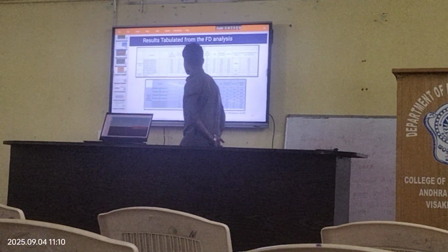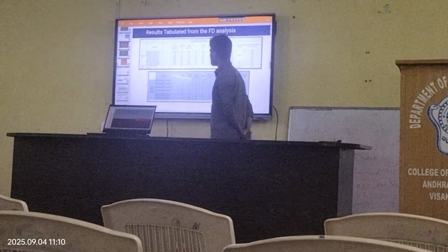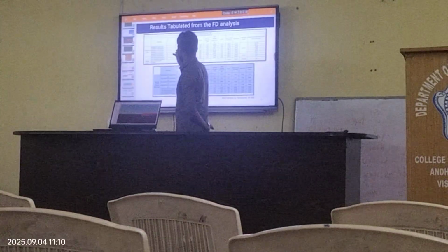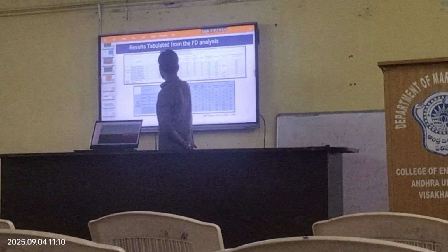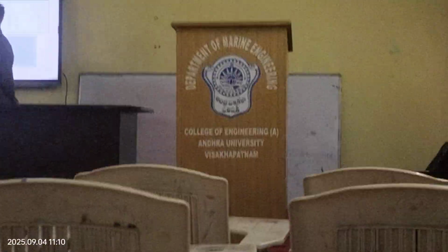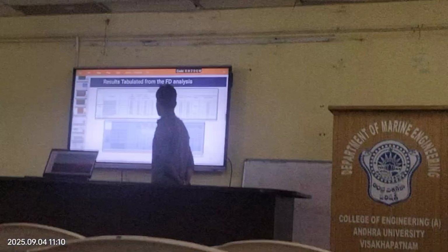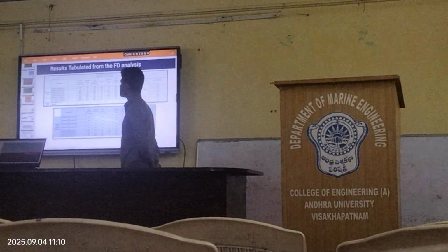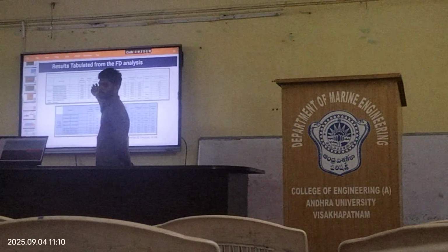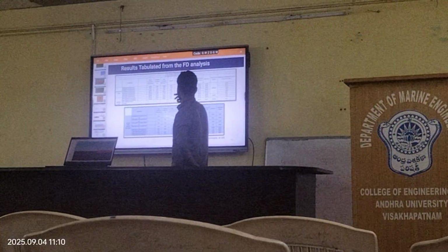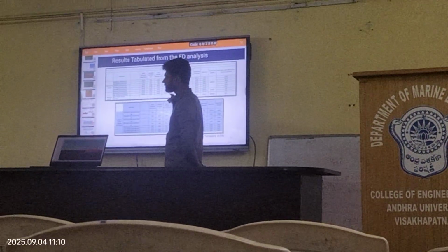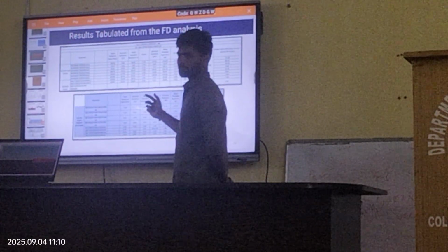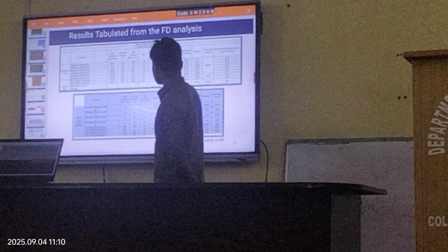And in the frequency domain analysis, these are the values I have got. In the frequency domain analysis, we first do the static analysis, then the standard deviation is connected with the LF. Then the most probable maximum values are taken from that, and the factor will be calculated. The factor will be the same, at most, in everything. Then the standard deviation of wave force. This is the low frequency and this is the wave frequency. The two are taken differently, and this is the most probable maxima in wave frequency. I use the Rayleigh distribution for this, and these are the factors.